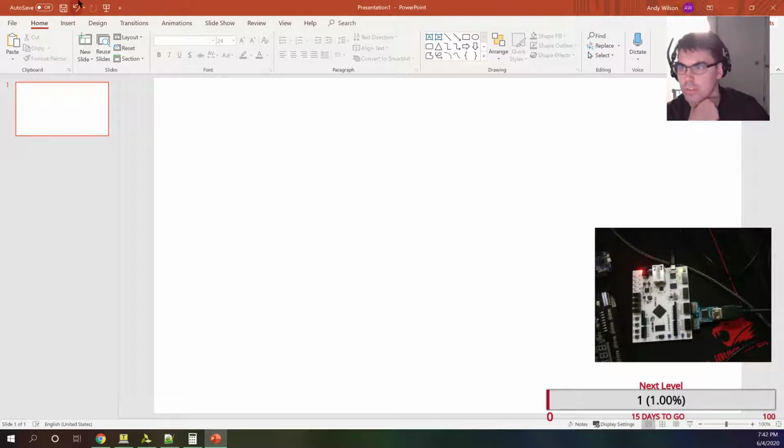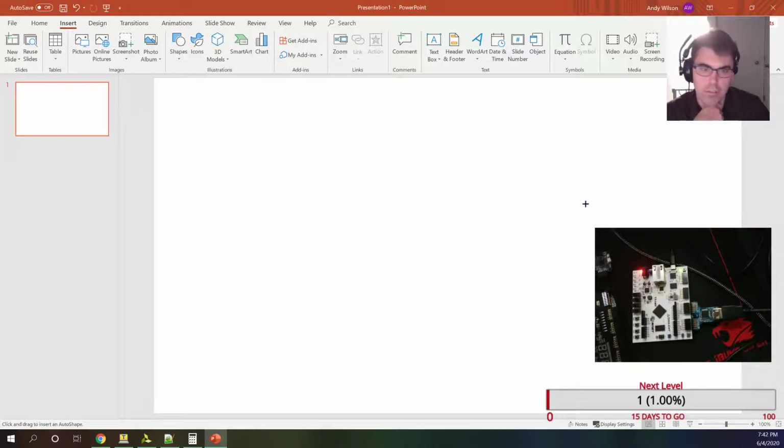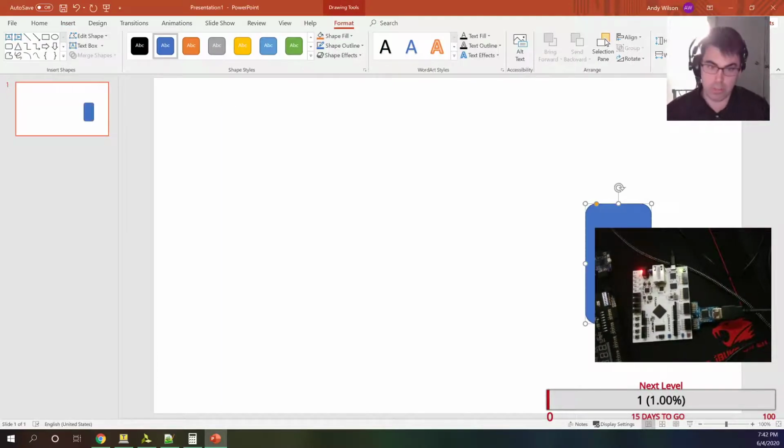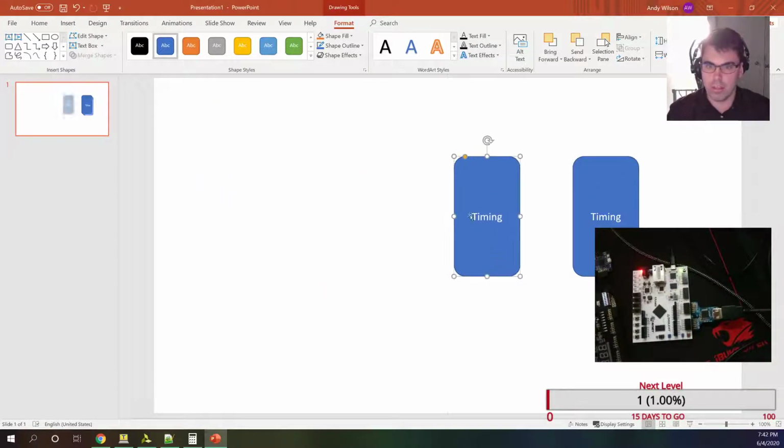we need some clock domains. How do we handle the other clock? We're going to need a dynamic clock if we want to do multiple resolutions. I mean, that might not be something bad to look into. So we're going to have like a timing core here. We're going to have an async FIFO.